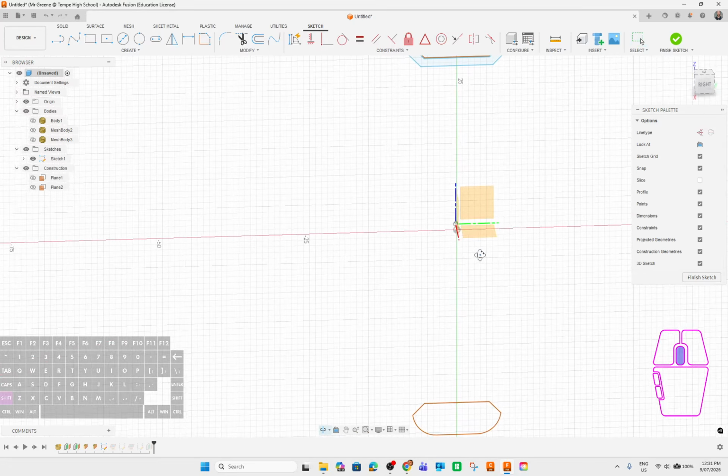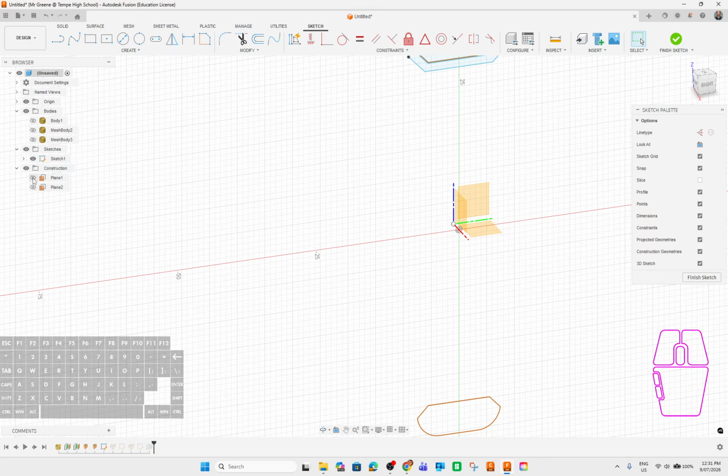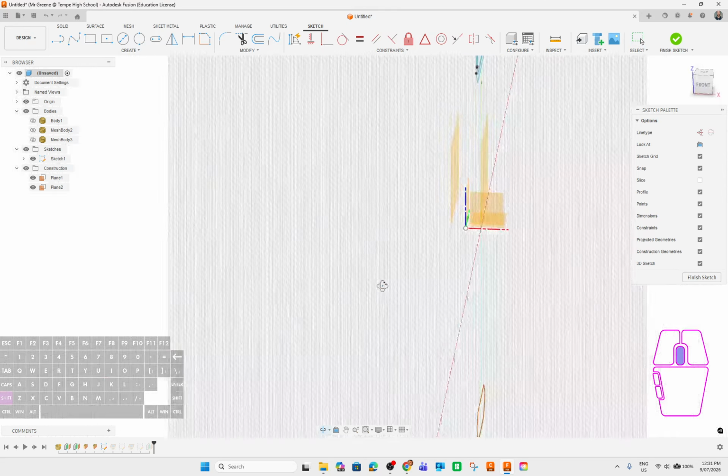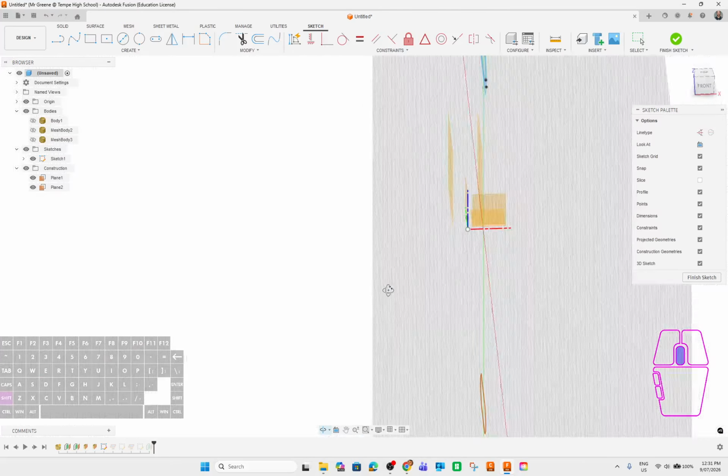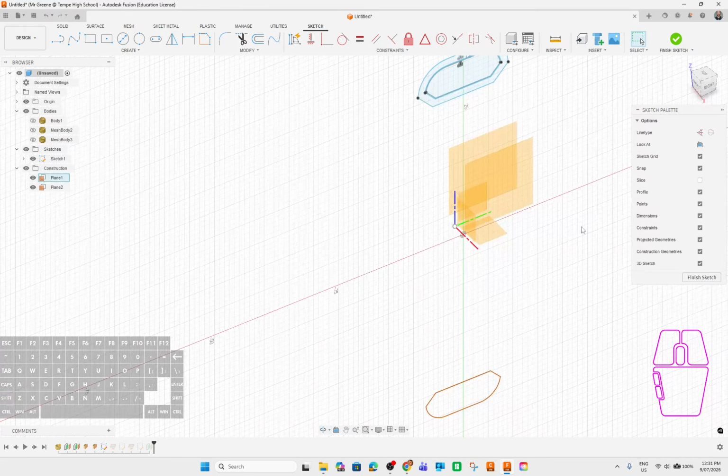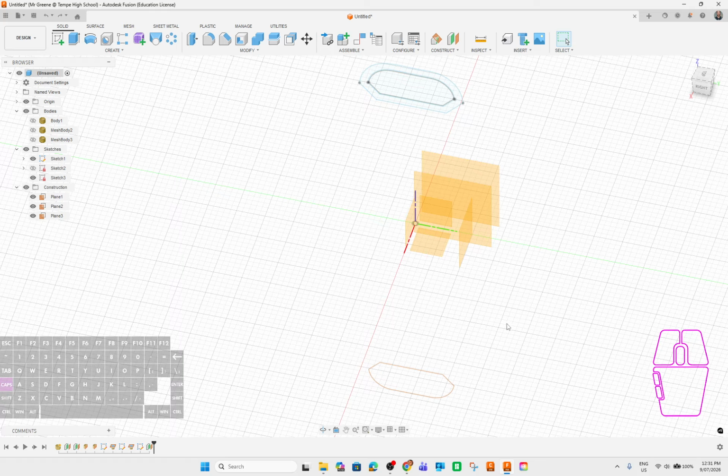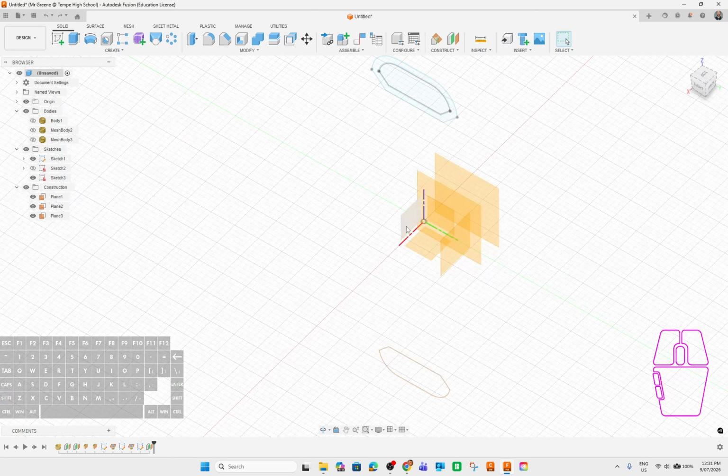But to do that, to make an axis, I actually need two construction planes. So I've got 1, 2 here, I think, but my axis actually has to go the other way. So I'll get back to you when that's done. To do that, I'm going to add another plane here. That's at 10 mils off this reference plane. The point I want to reference is just there.